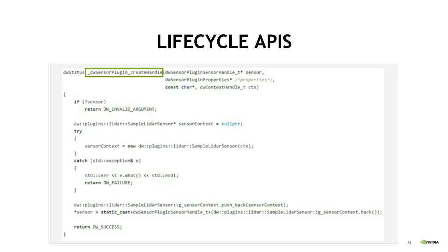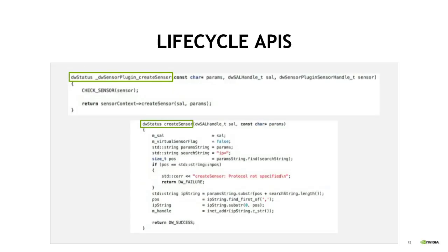The create sensor function is only called in the case of live sensor operation. This function should perform all necessary groundwork to start the sensor. In case of our implementation, this function only performs basic parameter parsing. As this is a TCP or IP sensor, we hold off on opening the IP socket until the start method to ensure stale data doesn't build up in the socket buffer.